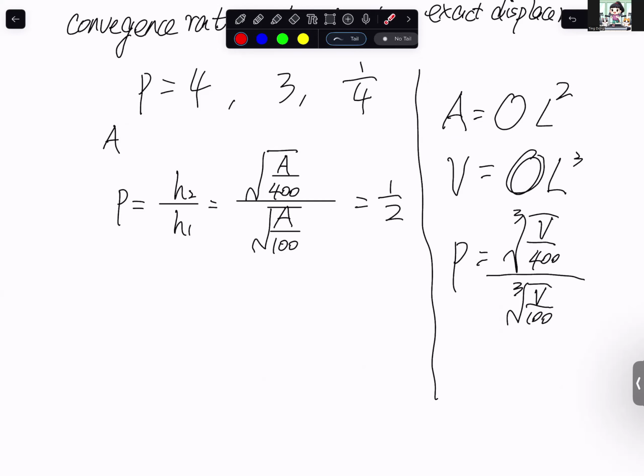We may have a combination of different sizes: in the area that we don't care about, we use larger element size, and in the area that will have the highest stress, we use more elements. But we normally do not use a combination of triangular and quadrilateral elements.